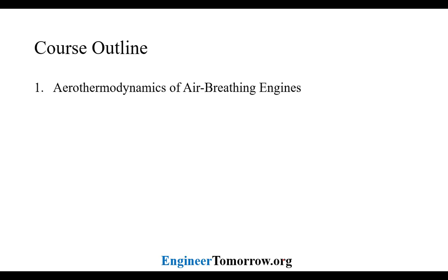So in terms of the outline, I'm going to talk about first the aerothermodynamics of air-breathing engines. So briefly discuss efficiencies, cycles, the types of engines, why you may want to choose one engine over the other. And this will just be a brief introduction to air-breathing engines. So next, I'll talk about, perhaps, one of the simpler topics in these engines, but they're still pretty advanced. There's aerodynamics involved in different geometry, but I'll talk about the inlets and the nozzles and how you can design those for subsonic and supersonic flows.